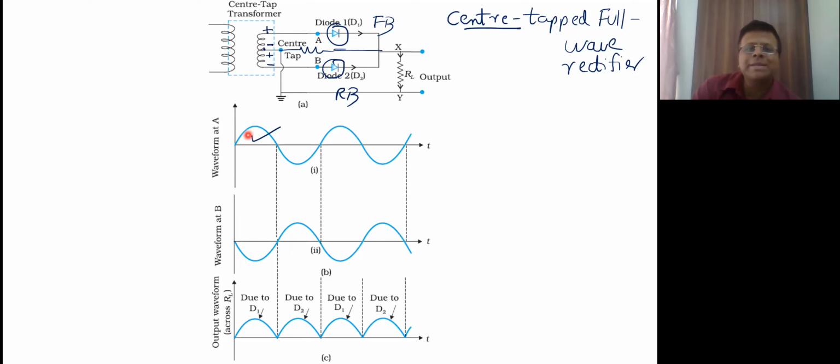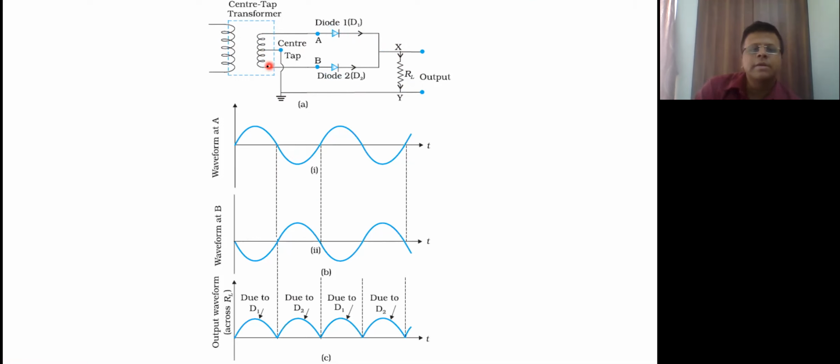Okay, so that means that in the positive half cycle, this diode is going to conduct and the current will flow like this. It will come here like this. Okay, and if I show it in this diagram, it will look like this, come like this, and complete the circuit like this. So this is the entire circuit, complete. And when I talk about the reverse direction, okay, then now instead of writing like this, let me rub this. It will look like this.